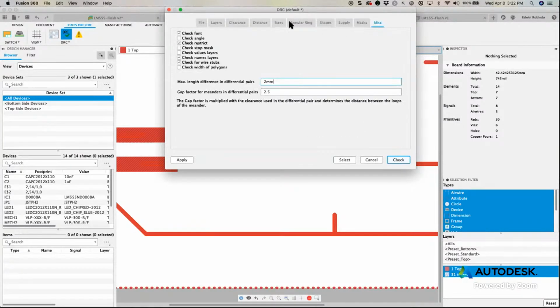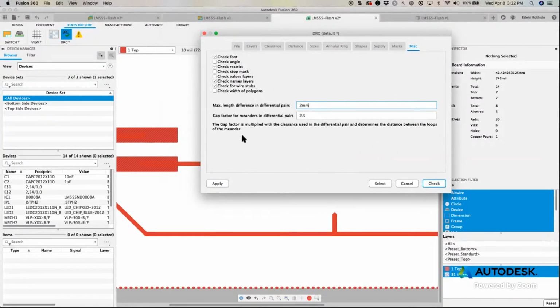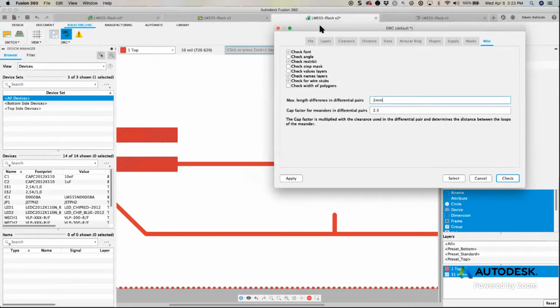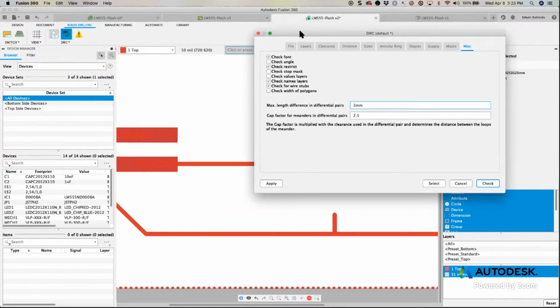Appreciate that. Okay. So now we talked about differential pairs and the gaps, but let's talk a little bit about what this is for: length matching. It's very commonly used for USB. I plan to do a small tutorial on how to actually use length matching. In essence, you need to name the signals with a particular characteristic. That way you have differential pairs. Then you could follow with a length match route and you could complete it with meandering. That way you have the exact same length. And this is usually done with DRCs. There are some other aspects of the board that actually require them because it cancels it out. So we'll work on that as well.